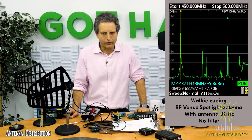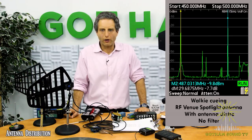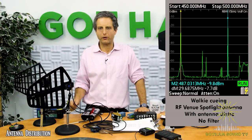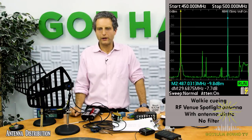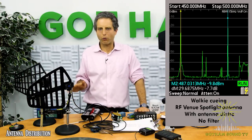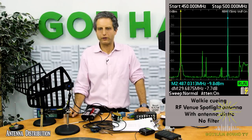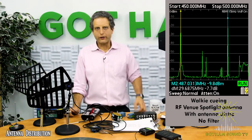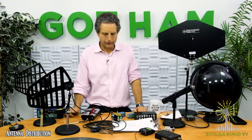Noise floor drops considerably. Interestingly, our desired signal actually goes up because that's the way this antenna is designed. The close signal gets received very well, and farther away signals don't get received as well. So noise floor goes down, and even our walkie signal goes down a little bit. So that's an example of less is more, and that's my design philosophy when I start to think about this stuff.